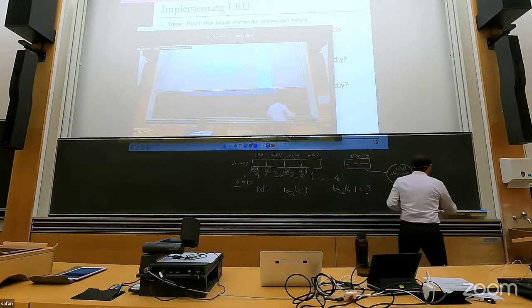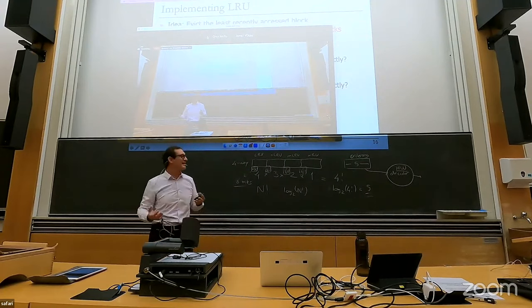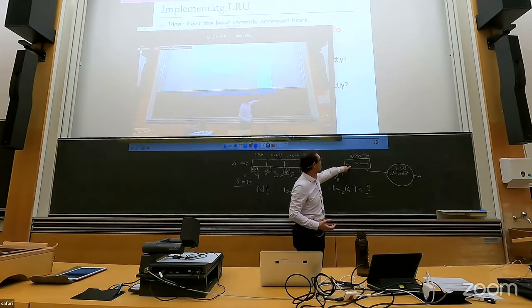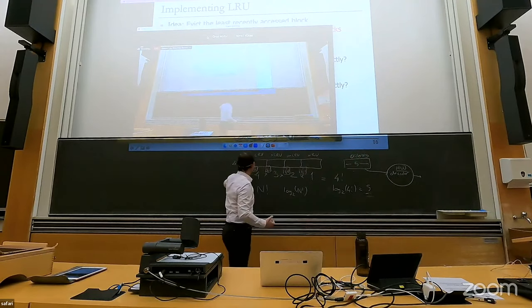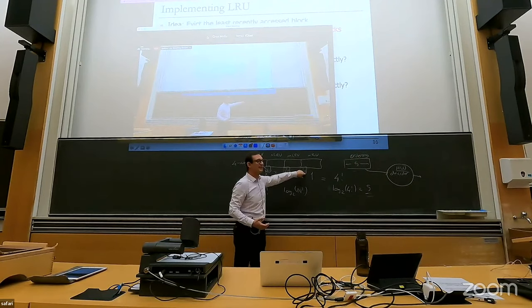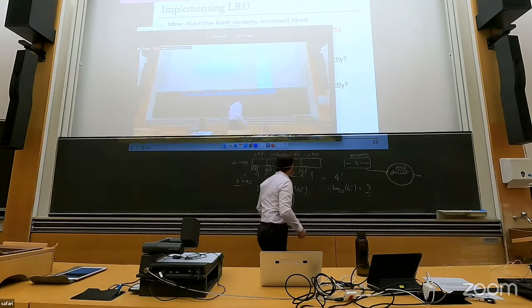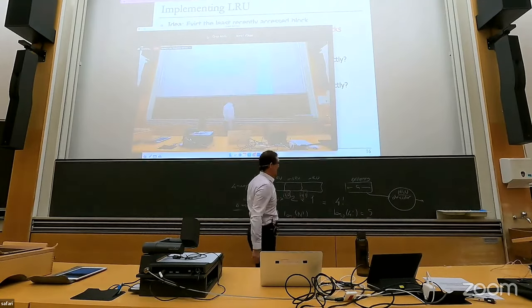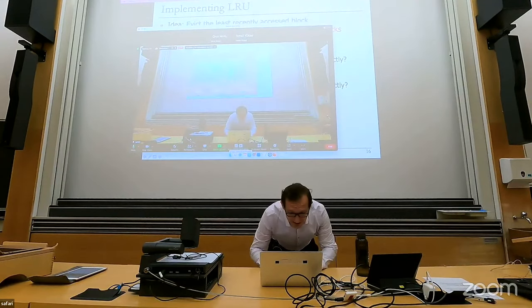Okay? So this is a trade-off, you always have a trade-off between latency and capacity. And this is another example of it. The capacity of storing the replacement policy bits is low in this case, but the latency of figuring out what you should really evict is longer because you need to go through that decoder. Here, the capacity of storing the replacement policy bits is larger. It's not the minimum, but the latency of figuring out what you should evict is actually much easier because it's already decoded, as you can see. Okay, so hopefully this gives you an example of why LRU is difficult to implement if your caches are highly associative.